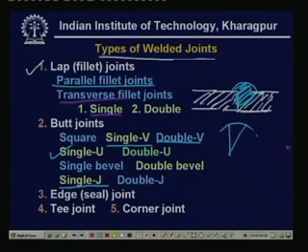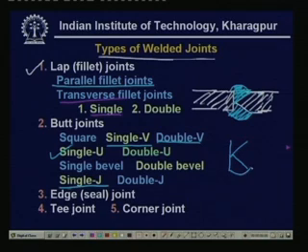We have the double bevel joint, very similar. This side as it is and here, and we add metal on this. So, this is the double bevel joint and the symbol is something like this. So, these are roughly the bar type joints.